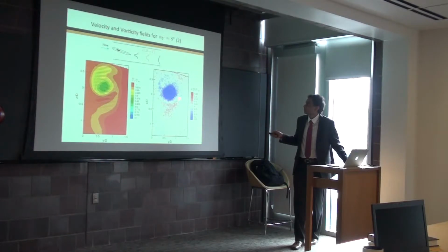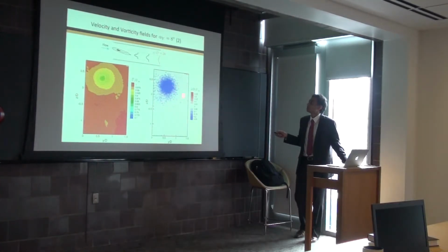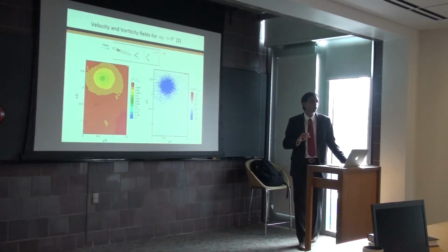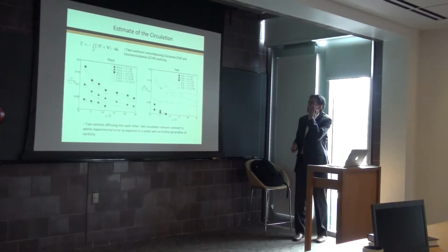That vortex footprint persists. This is slightly different to pitch. Even at the final downstream location, the footprint of that vortex is very strong and remains because it convected downstream relatively undisturbed relative to the pitch case. So this is an important distinction between pitch and yaw.